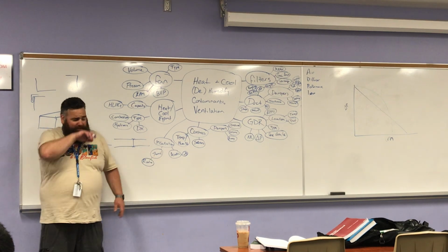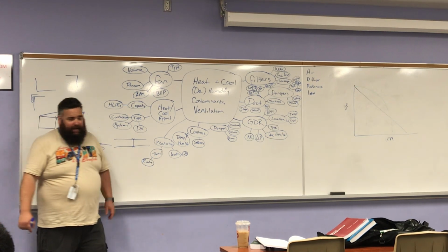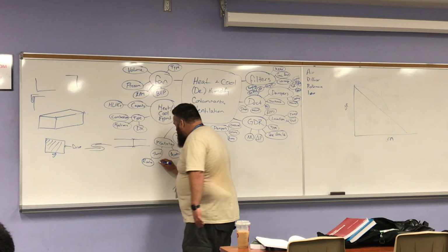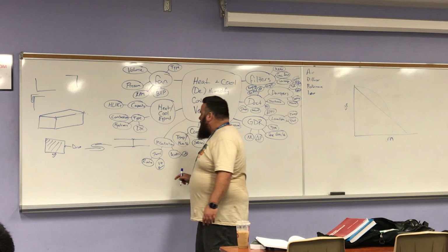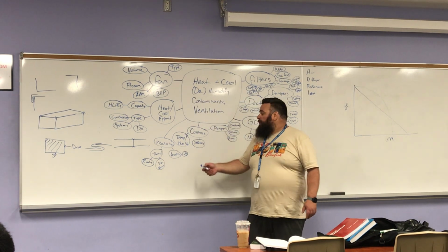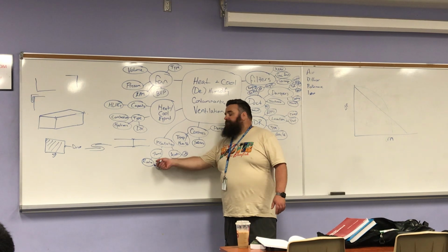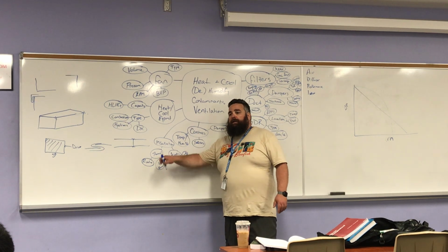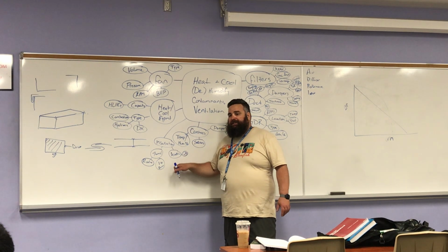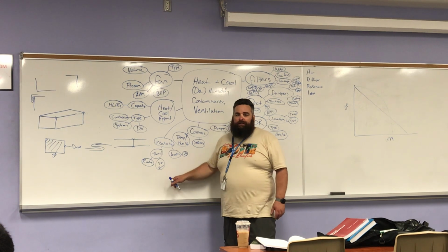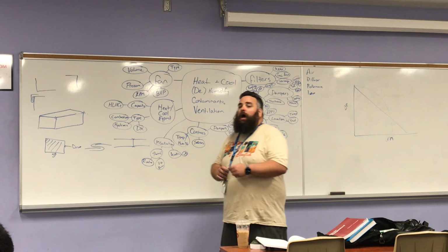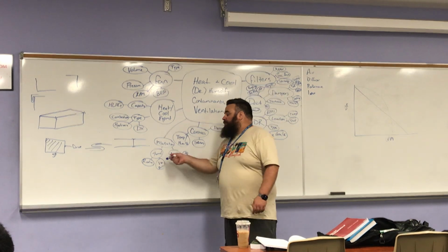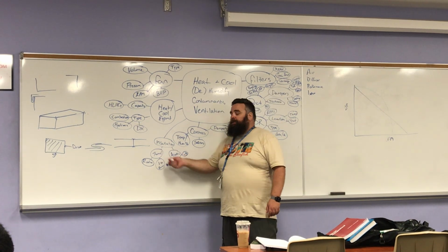The other thing thermal insulation has is a vapor barrier. And that is, in my opinion, even more critical than R value when we're comparing thermal insulation versus acoustic insulation. The reason I bring this up is because in my career on the design and construction side, I've heard time and time again, we do not need to insulate that duct.